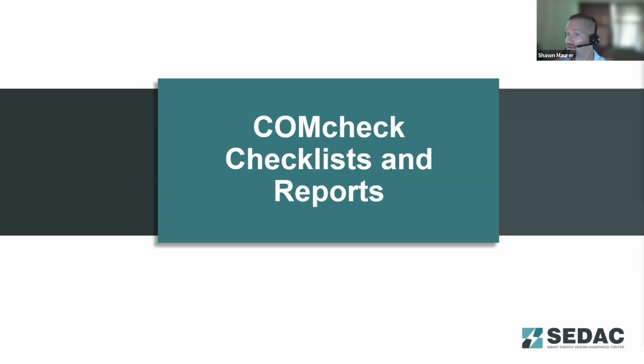If you're following the straight prescriptive path, where you're just following the prescriptive requirements of the code, you don't need to do a COMcheck or REScheck for that. You could do a compliance checklist based on the energy code requirements. And if you're doing the performance path energy modeling, where you're documenting through an eQuest model or Trane TRACE, Carrier HAP, those programs that do whole building energy calculations for performance analysis, then you don't need to do a COMcheck or REScheck.